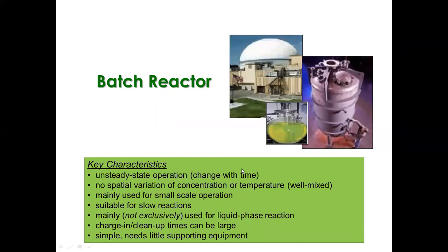The thing with batch is it's like you're cooking something: you put everything inside, you allow it to react based on the time that you want it to react, then you withdraw it. So the charging and the draw off time, together with the cleanup time so that your particular reactor can facilitate a different type of reaction, is a thing to be considered with a batch reactor. So time for putting in the reacting species, time to withdraw the product, and time to clean it up for the next operation. That's a drawback also for your batch reactor.